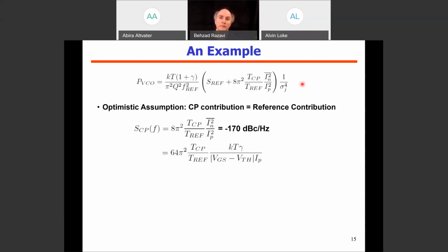Got it. Okay. And I guess a couple more questions. So one question, technology. As we're moving towards these technology nodes, we have 5 nanometer products already in production. Clearly, the flicker noise contribution is soaring to the roof. I mean, we're seeing for the very small devices, corner frequencies into the gigahertz range already, right? So, factoring that in, how do you see these trends playing out?